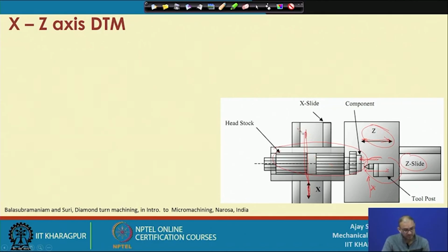Because many times, as we will see in some applications, and we have seen also in the fabrication of those micro molds, at that time your machining was done at this location. Your tool was not stationary, but was considered a milling tool. So, it was rotating at a high RPM, then you do machining here, then you want to shift to this location, and instead of the tool moving in this direction, your whole job was moving in this direction, right. We will see that video again.